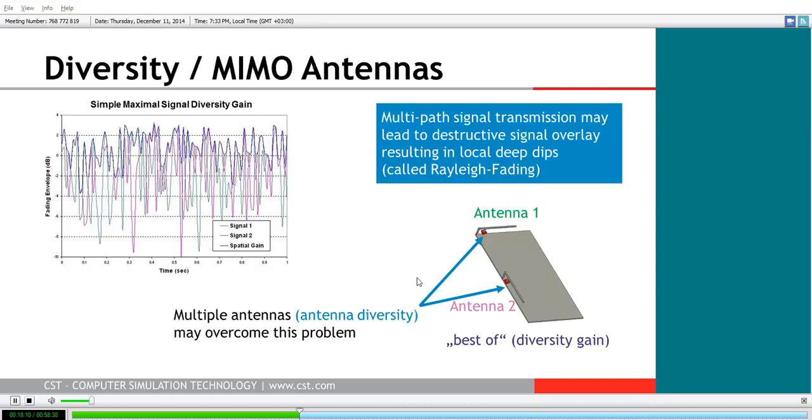So you can see here just a very, very simple MIMO antenna where there is a bit of spatial diversity as well as a polarization shift for these pair of PIFA antennas. And you can see in the resulting received signal, because we have these two relatively decorrelated signals, when one antenna is subject to a fairly large path fading dip, the other antenna is not, because it has low correlation. And as a result, the signal that we actually receive, we can opt between the best of the pair, and we get an effective gain from this diversity.